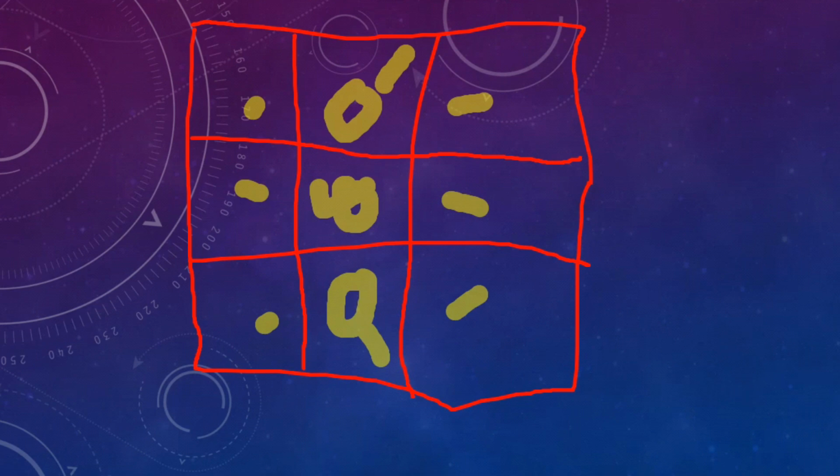You need to understand that there is no fixed rule for the minimum or maximum distance I have to maintain; practically it's adjustable based on the site. You have to make sure that at least 1.5 meter is maintained if possible. But if it is not possible, then okay, it's acceptable because it's a practical thing. We cannot fix the rule that 1.5 meter must always be maintained. Instead of my diffuser, you would need to adjust the sprinkler, and that is not possible. So in this case, we have to have 4 diffusers, 2 supply and 2 return.